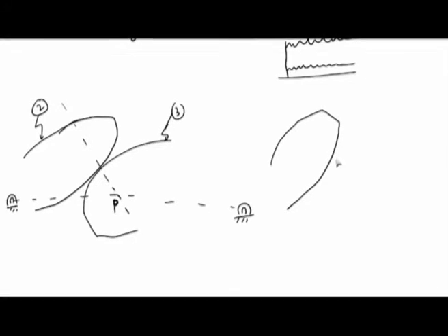So, at a later instant, let us say the gear has rolled, and this is where the engagement is taking place. The shaft centers again lie somewhere here. Again the relative instantaneous center can be located as the intersection of the line joining the shaft centers and the common normal between the two surfaces in contact. So, again this is the point P. This is instant T1 and this is instant T2.